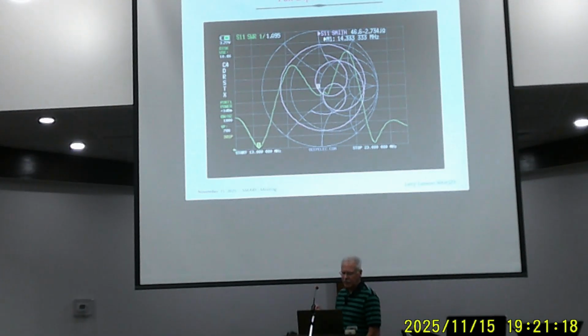at every frequency. So as you move that marker around on the green one, say if you drag that on the green SWR trace, it'll also move that on that purplish trace. And each one of those will tell you what's going on.